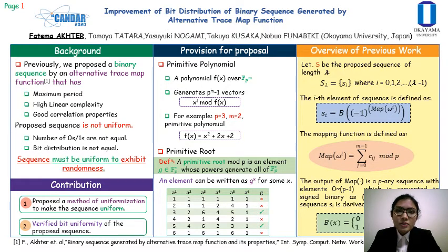Pseudorandom binary sequences are generated by a deterministic algorithm but exhibit randomness. For a pseudorandom sequence, it's difficult to predict the next bit from part of the sequence. Using the same parameters, the same sequence will be generated. For this convenience, pseudorandom sequences are preferable to their counterpart, truly random sequences.